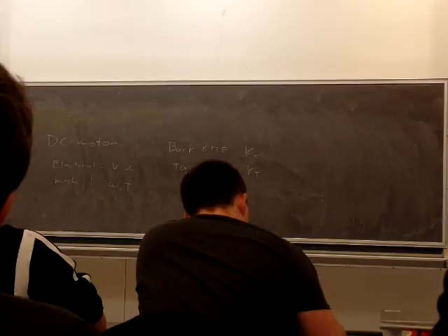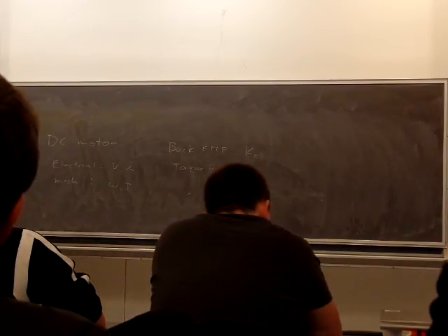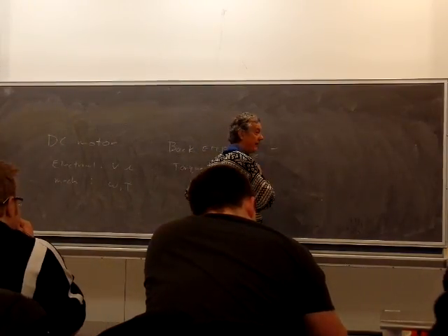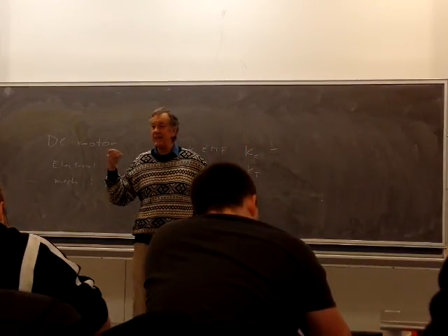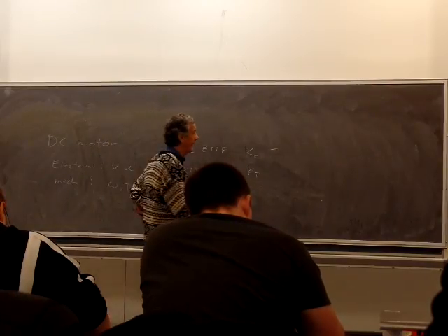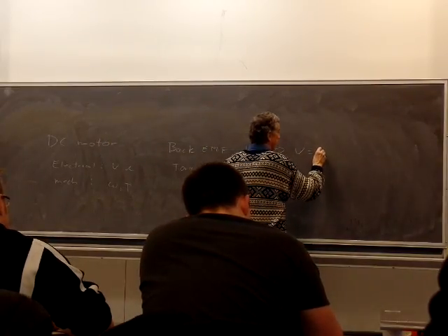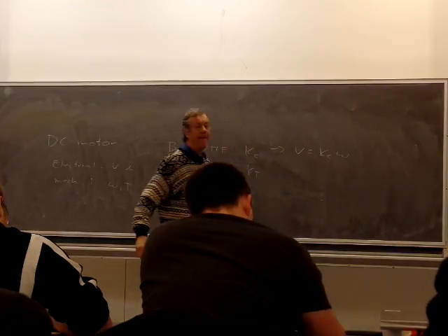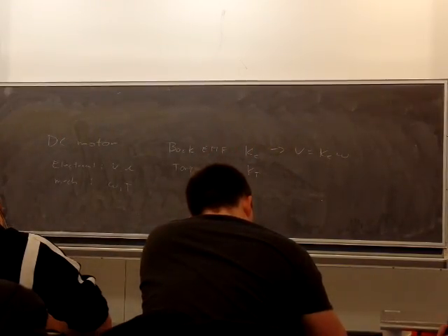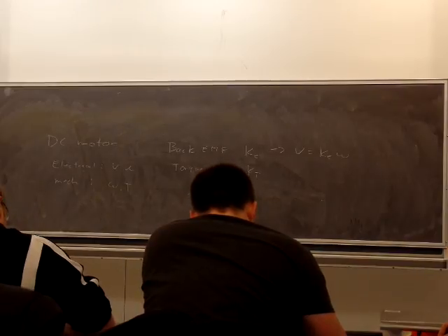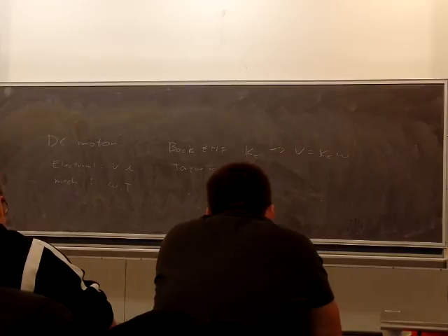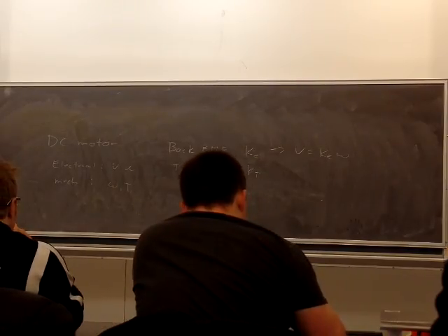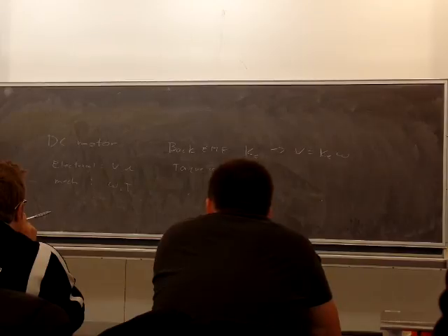Voltage and speed. Voltage and speed, all right? Remember that relationship? K times omega. All right, well, the voltage is equal to what? K_E times omega. What are the units of K_E? Well, they've got to be units of what? Voltage over radians per second. Volt seconds.